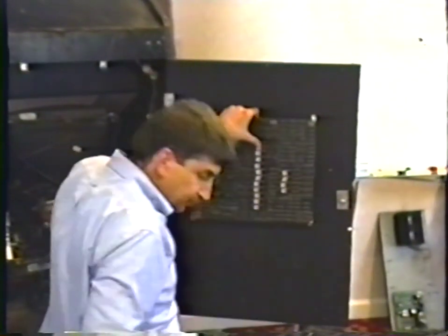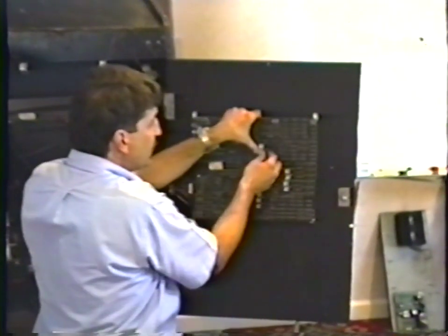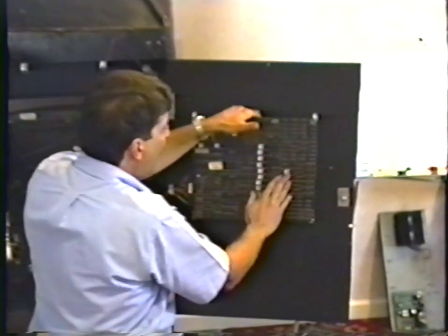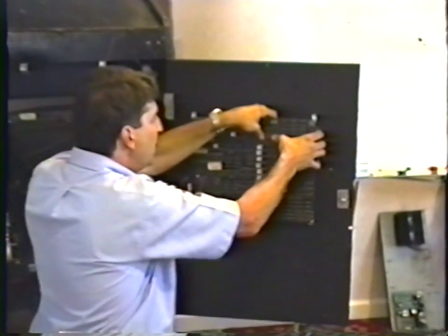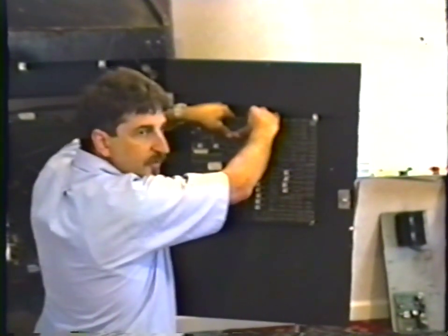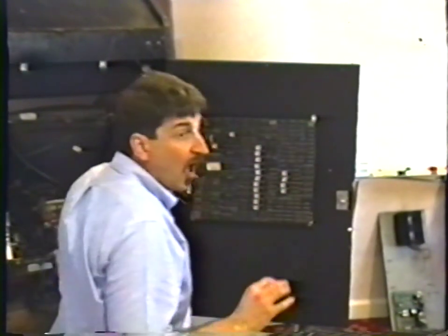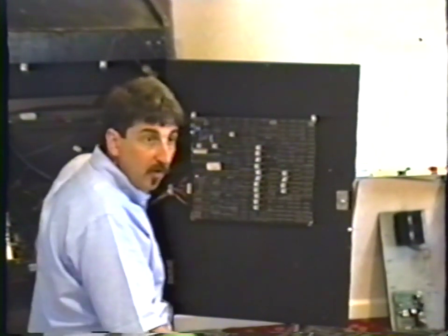Anyway, one at a time, you pull out the integrated circuits carefully, prying them out with a screwdriver, and put them all back in. It'll take a little bit of time, but for instance, on Pole Position, which we operate a lot of, I have to do this about every year, pull all the chips out, put them all back together again. And that solves a lot of board problems. About 20-30% of my board failures, that's all I do.